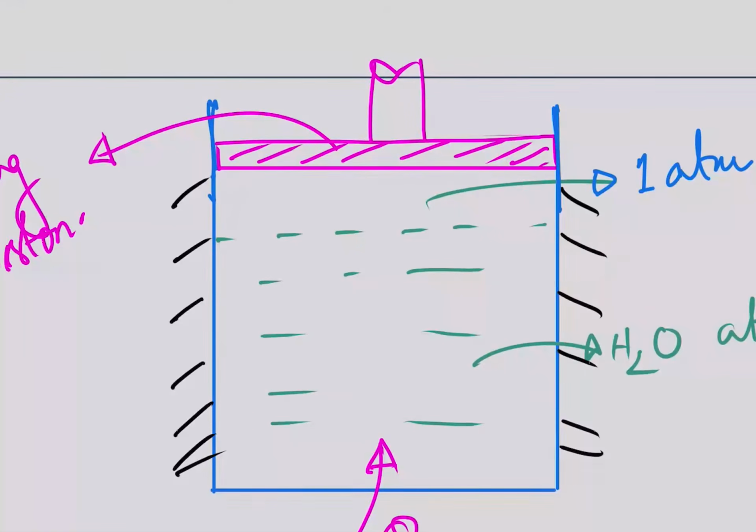Can I have a quasi-static process which is irreversible? No, a quasi-static process is an internally reversible process. What do you mean by internally reversible process? It means there will not be any losses occurring inside the system, no irreversibility associated within the system.